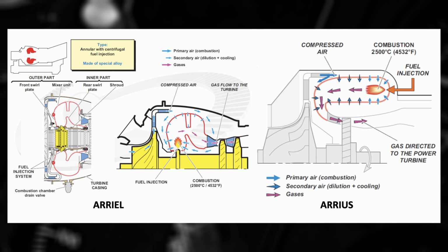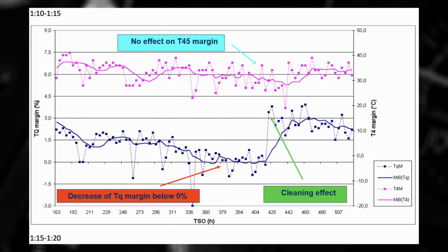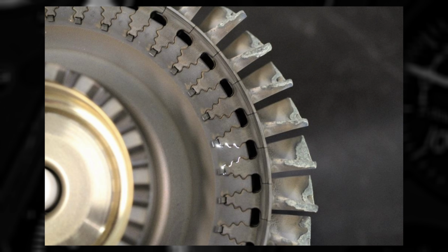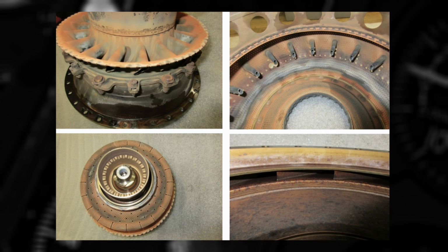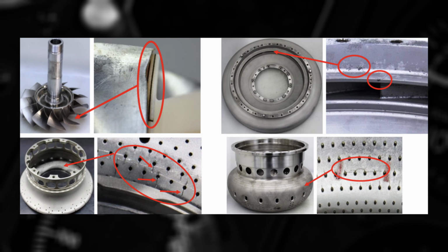So why does the air path require cleaning? A dirty air path reduces the efficiency of the gas generator, which results in lower power margins or incorrect power checks. It also leads to damaged internal components, resulting in a significant increase of expense at repair or overhaul. Parts with life remaining that would be otherwise serviceable must be scrapped due to preventable damage.